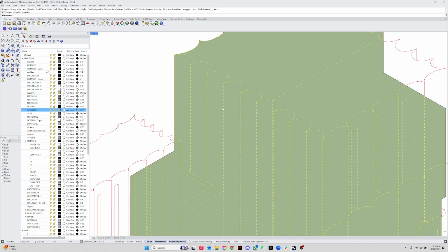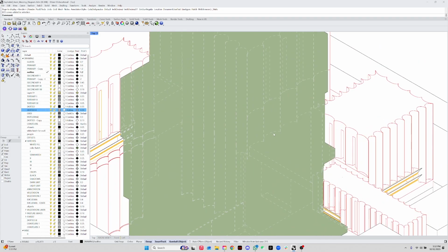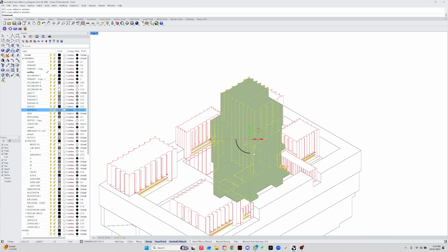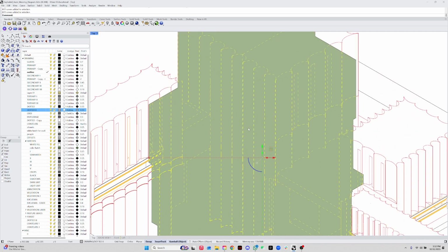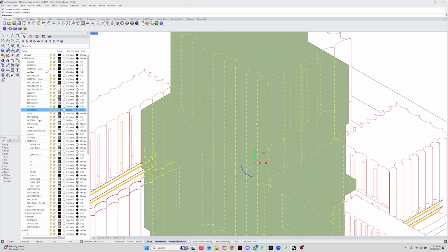So again, either do it this way or you can do it the way that I was showing you before, which was keeping the same line weight, but just changing the model space scale. So I'll leave that up to you. And if you want to have multiple different lines that you can switch back and forth, then you can. But at least for this, you're only going to need one dash line type. So I would either create one type or I will stick to just using the model space dash lines.